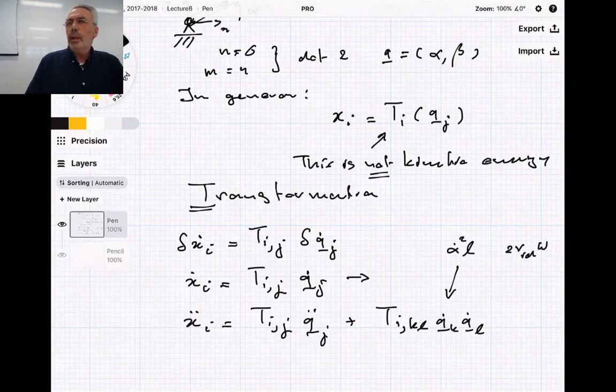That is, if you have some moving coordinate system, so generalized coordinates, and within that moving coordinate system you have a relative velocity and the coordinate system is also rotating, then you have some magic acceleration which they call the Coriolis. Yeah, it's no magic acceleration, it's just a convective term.